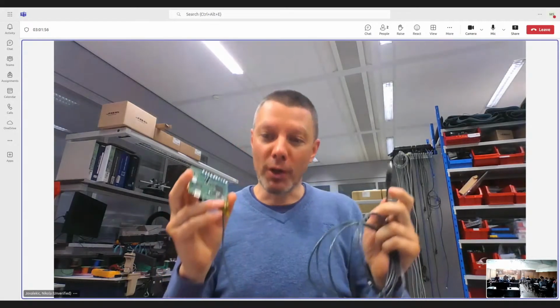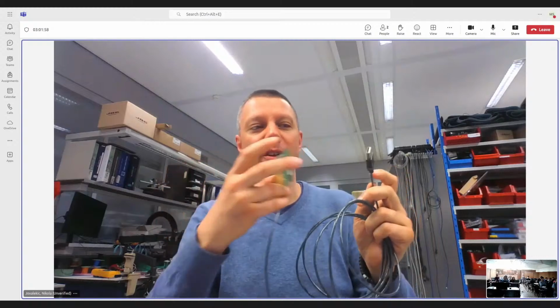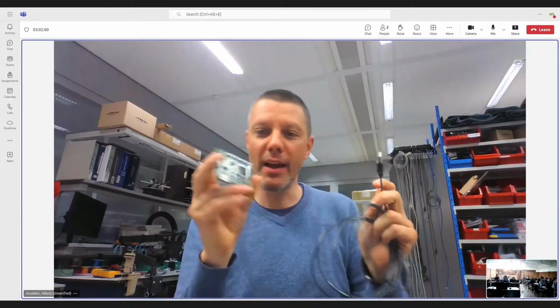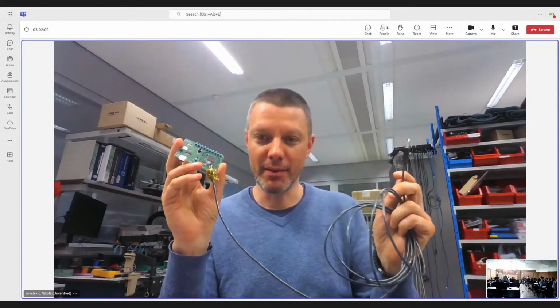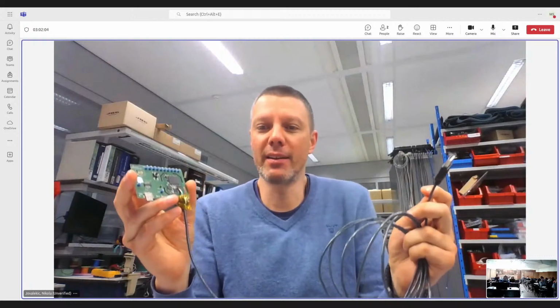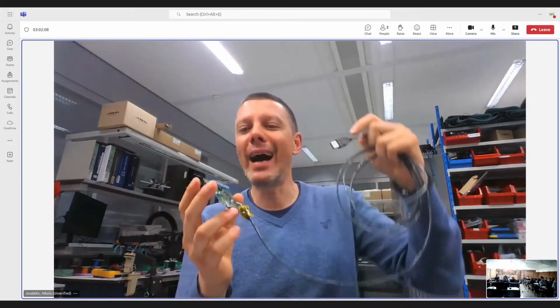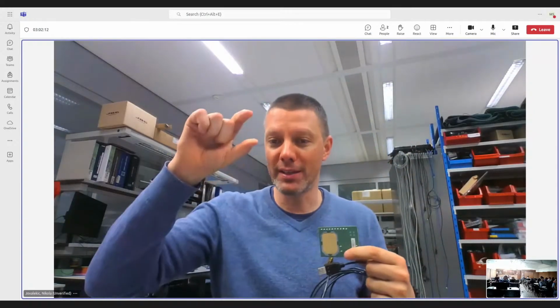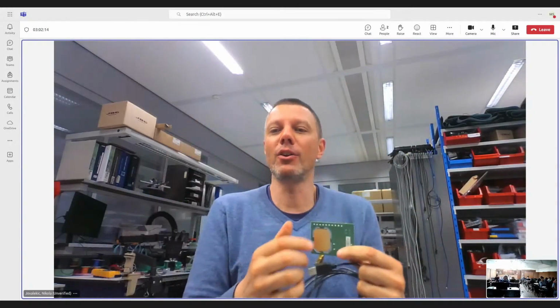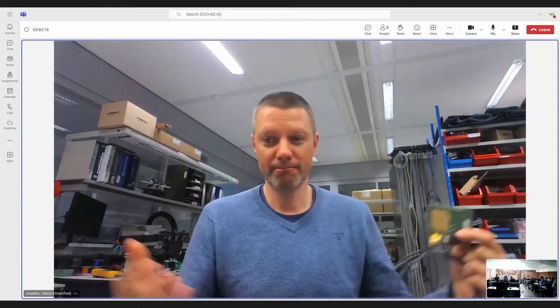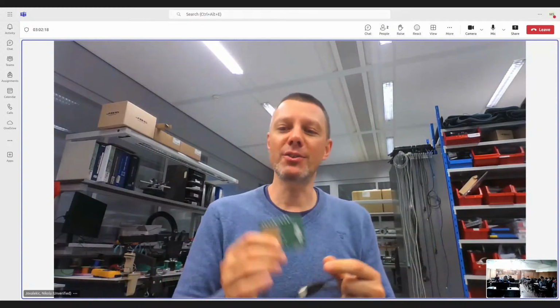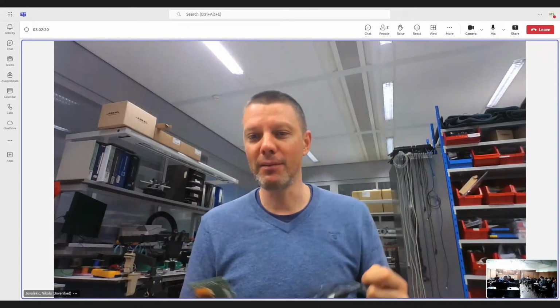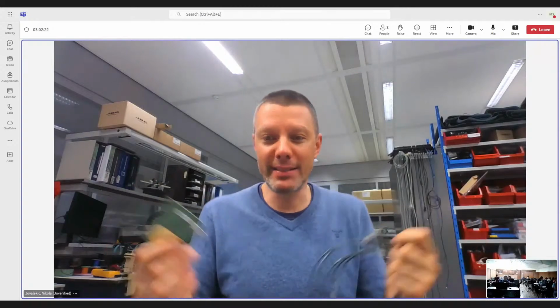So we want to see what will happen when we want communication between the notebook and this embedded system. What will happen with our signal if we have communication, because maybe the eye diagram is too closed. Actually, the amplitude of the signal is too small, and we cannot decode the signal. We don't know that. We just got this PCB today, for example, and we want to test it.